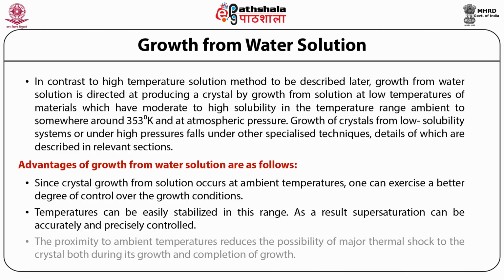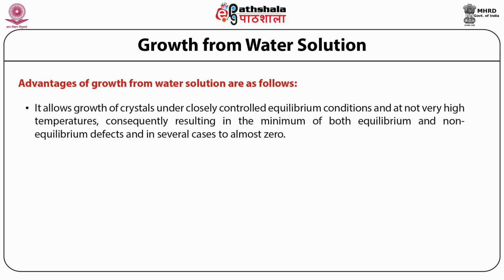Number three, the proximity to ambient temperatures reduces the possibility of major thermal shock to the crystal both during its growth and completion of growth. Number four, it allows growth of crystals under closely controlled equilibrium conditions and at not very high temperatures, consequently resulting in the minimum of both equilibrium and non-equilibrium defects, and in several cases almost zero.